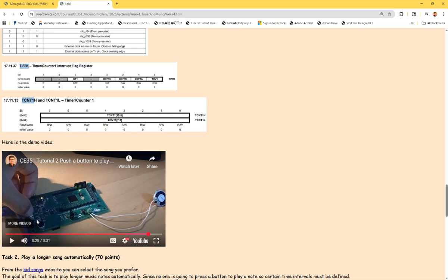So it's a very good way to verify, because the microsecond delay is actually the one we found from the oscilloscope. Okay, so we assume that it is accurate, and then we use a microcontroller's timer to do the same oscillation, and we hear the same tone, or same pitch. That means the microsecond delay function we found from the oscilloscope is accurate. Maybe there will be tiny differences, but at least your ears cannot tell the difference. You know what I mean?